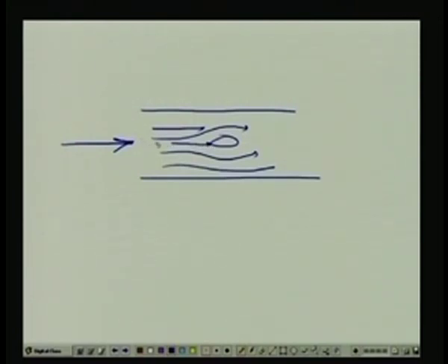So, the liquid which is coming to rest in contact, what will happen? The fluid will be decelerated when it is approaching this solid body. At this point it will be totally stopped. So, the velocity of the liquid at this point will be exactly 0, and the velocity of the fluid, suppose this is V. So, this liquid is also flowing with velocity V, then it is flowing out, right. But just in front of this one, if you look at this position, the fluid will come to rest.